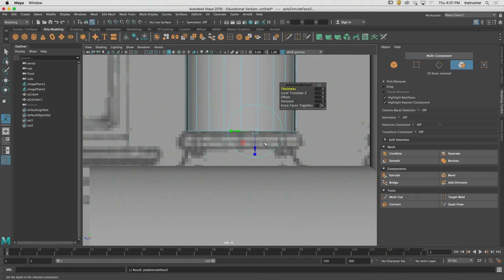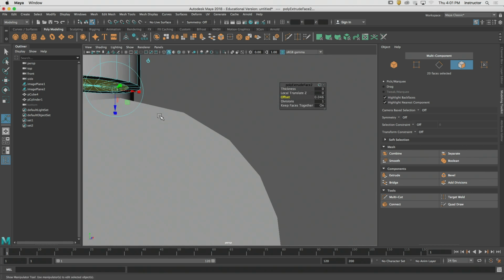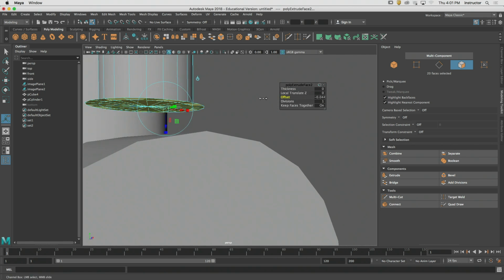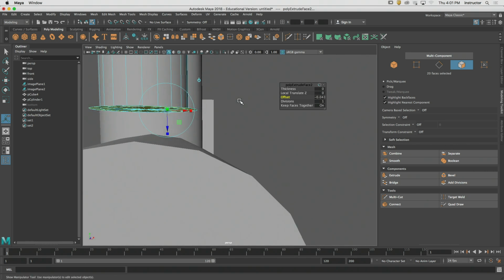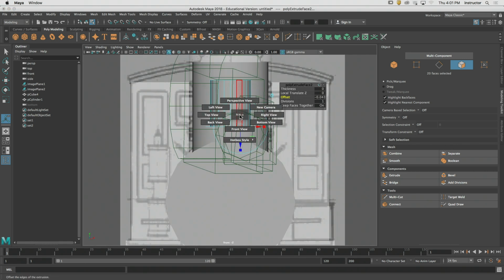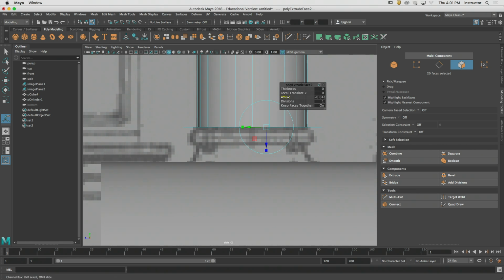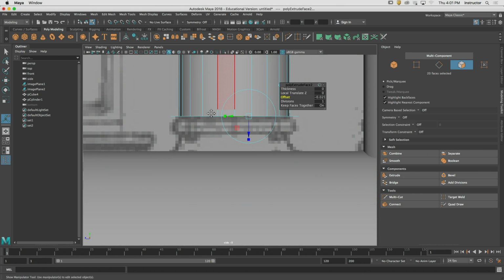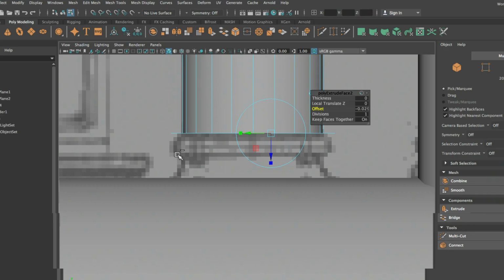I'm going to use the extrude tool. And of course, I'm going to grow, let's see, go in the opposite direction. I always do that, by the way. There we go. Now I'm going to extrude this shape until I think that vert, the one that's right there on the corner, is kind of in line with the outside of this band. Okay.